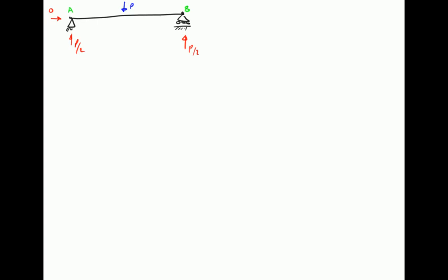Okay, so we established a shear force diagram internally for those beams, where the shear forces were giving rise to internal equilibrium of the externally applied forces due to the actual load P and the reactions to that load at the supports at A and B, P upon 2, each of them. We're now going to look at the internal bending moment, which is given rise to from those external loads.